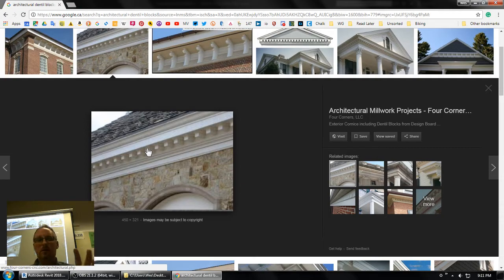So if you're going to build this whole thing and make a really high-powered family, what you would do inside the line-based family is have an extrusion that has the profile of this trim board and the piece that's overhanging. So this whole thing would be one extrusion, but to get these blocks in place, you'd have to do an array.